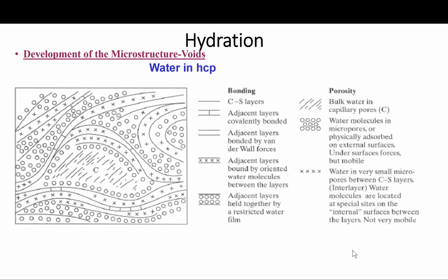So what is the impact of the water in the voids on the structure of the paste? Under electron microscopic examination, voids in the hydrated cement paste appear to be empty. This is because the specimen preparation techniques call for drying the specimen under high vacuum.